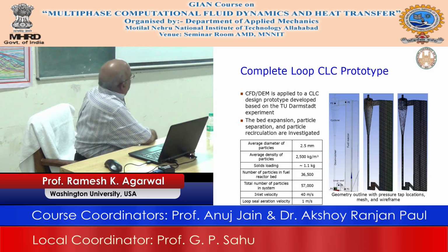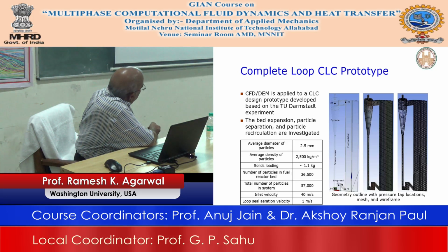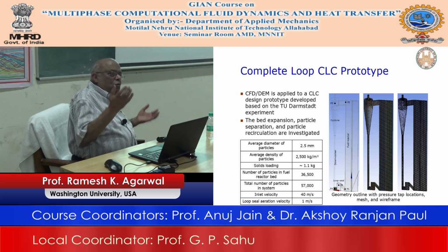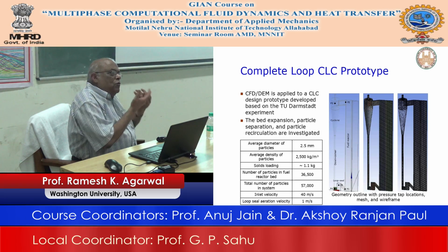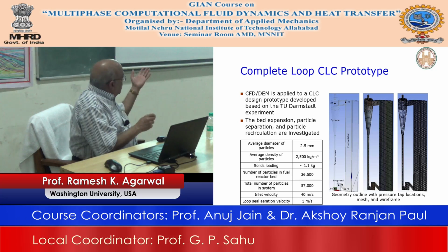So what is happening here is that this is the fluidized bed. The flow comes in, all those bubbles are generated, then they burst, they come around. This is called the cyclone, and then it comes down, and this is called the loop seal. That is how we call it. And this is a complete loop. It turned out that the circulation of that Fe3O4 is not working. The particles are not able to circulate. It gets stuck somewhere or the other.